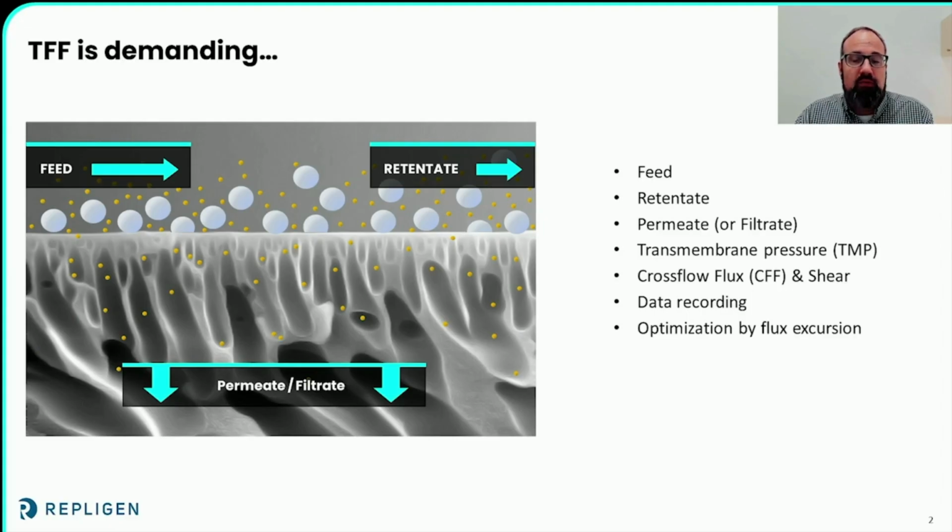So tangential flow filtration, as you likely already know, is a very reliable, widely accepted method to clarify, concentrate, or perform a buffer exchange of bioprocess solutions. The basic concept is to recirculate a solution across a membrane under very specific and repeatable pressure and flow conditions. This enables the membrane surface to remain relatively permeable throughout the process, despite the solution concentration or changes in viscosity encountered. Most importantly, the TFF concept enables a high level of product recovery.